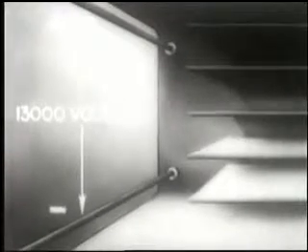Magnesium from seawater is another achievement of industry under the stress of war. Ignitrons used in the extraction process speed up the delivering of incendiary and demolition bombs to the centers of Axis production. Still another example of electronic rectification at work is the precipitron, a device for cleaning air electrostatically. This diagram explains how the precipitron works. The rectifying property of electronic tubes is used to apply a potential of 13,000 volts DC to tungsten wires and 6,500 volts DC to collector plates.